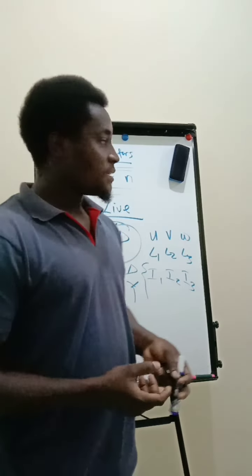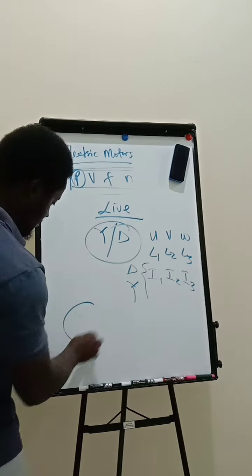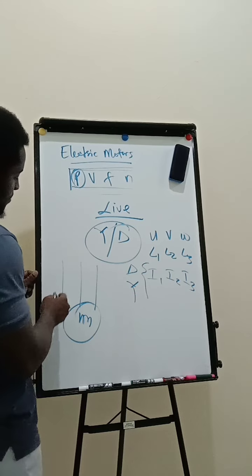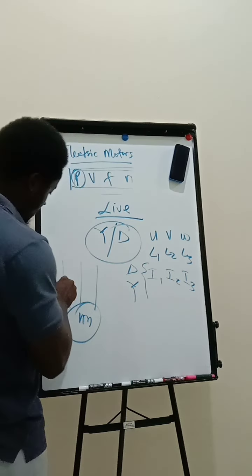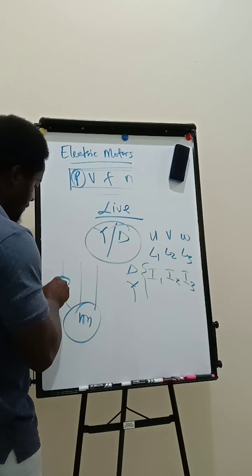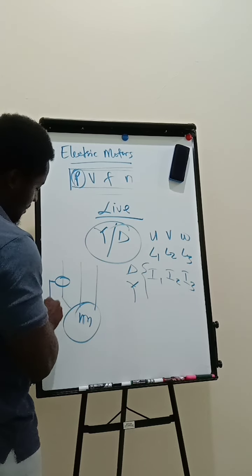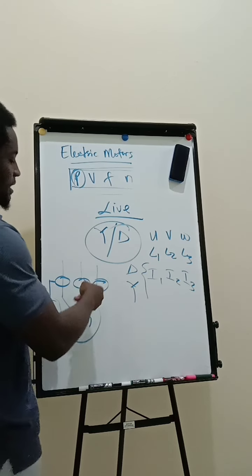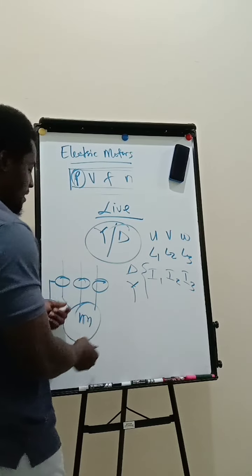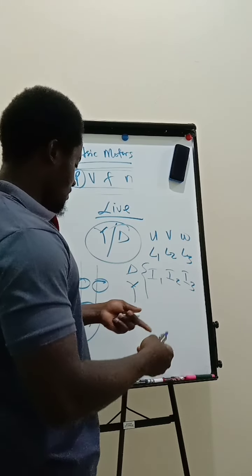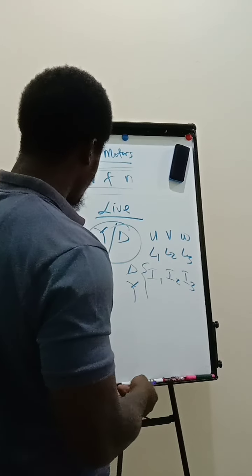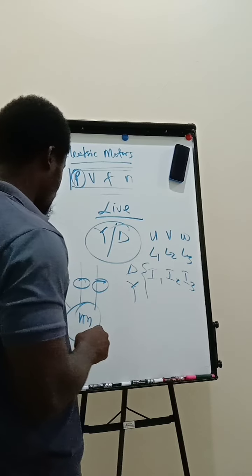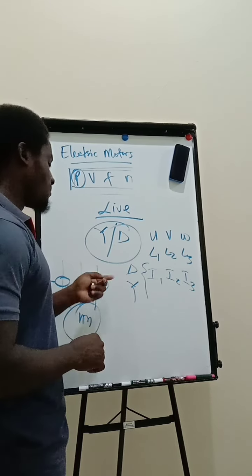So what we have to do is count the different phases. For example, this is the electric motor, and we've given power to it. At this point, we take our clamp ammeter, connect on each of the different phases, and take the reading. Then we go to the next phase and the next phase. Take down the different readings for star, and then after some predetermined time, it will switch to delta. We take the different currents also for L1, L2, L3, or U, V, W windings.